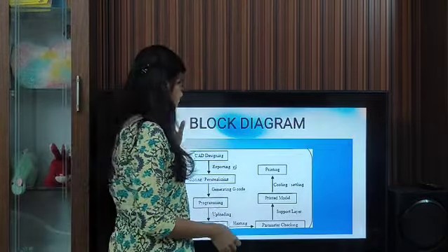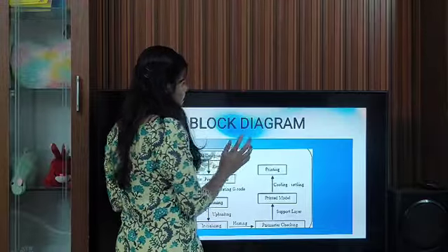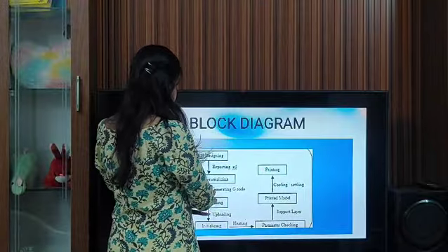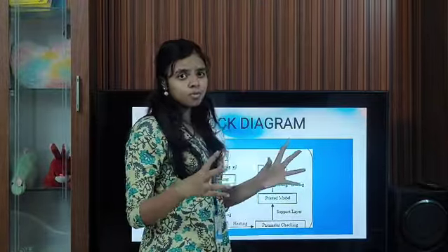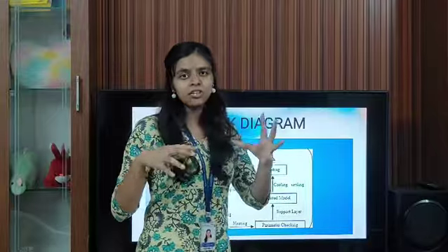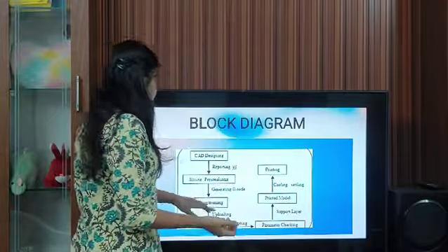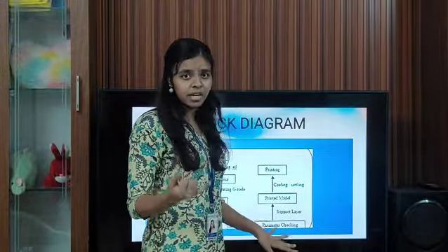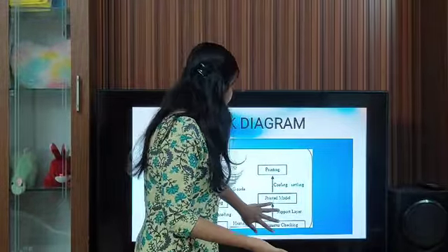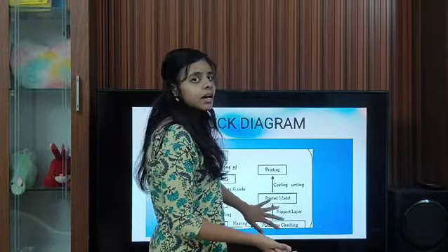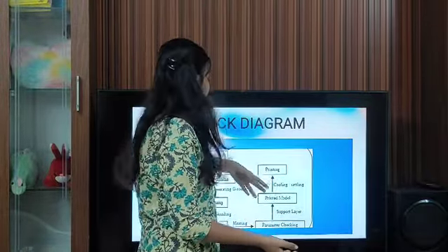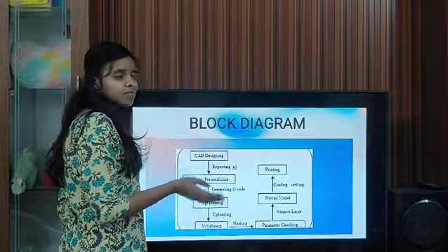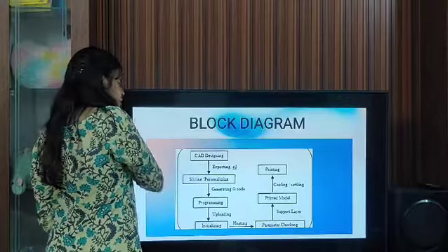Block diagram of 3D printing machine. CAD design: designing the object using the CAD software and exporting it. Slicing the object helps in generating the G code, and then this program is uploaded into the printer. Then the printer checks the parameters of the X, Y, Z axes, and then the model is printed, and then the printed model is cooled, and then the cooled model is finished, with whichever process is needed, sanding or finishing.